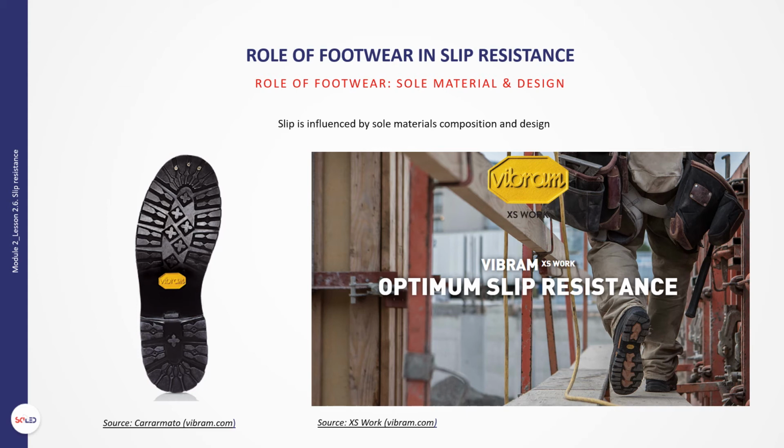If the channel is too small and thin, the space may not be wide enough to channel liquid to the outer edges of the outsole, potentially increasing the chance of a slip or fall. Similar to the tile design, a channel with streamlined design should help the contaminant drainage and improve the slip resistance. In order to create even better traction, some designs choose further small channels that divide each cleat into 3 or 4 movable parts, hence further increasing the grip effect.